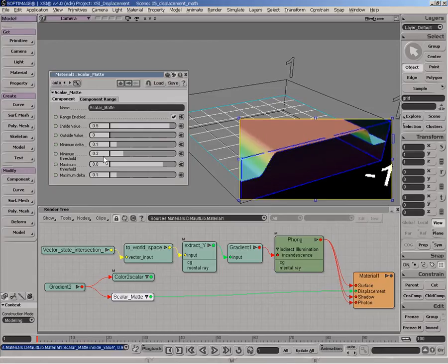out of this grayscale. So what I'm saying to this shader is, anything that has luminance greater than 0.2 but lower than 0.8, I would like you to extract this and return 0.9 as the output. So this creates this sort of luminance extraction. So I can actually make the minimum and maximum delta, which is the delta between this value. So this is 0.2, this is 0.8, and these 0.1 are basically the falloff that occurs on both sides right here.